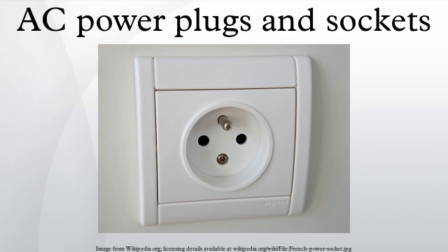Italian multiple standard sockets. In modern installations in Italy it is usual to find sockets that can accept more than one standard. The simpler type has a central round hole and two figure-8-shaped holes above and below. This design allows the connection of both 10A and 16A plugs and the Europlug. The advantage of this socket style is its small, compact face. VIMAR brand claims to have patented this socket first in 1975 with their Ascent model.